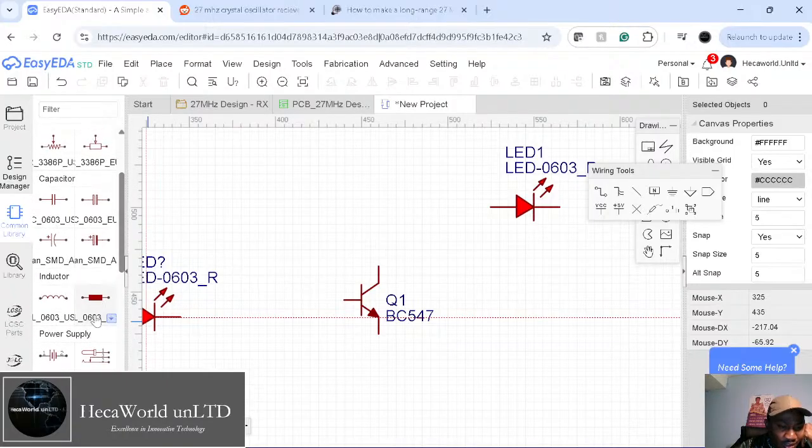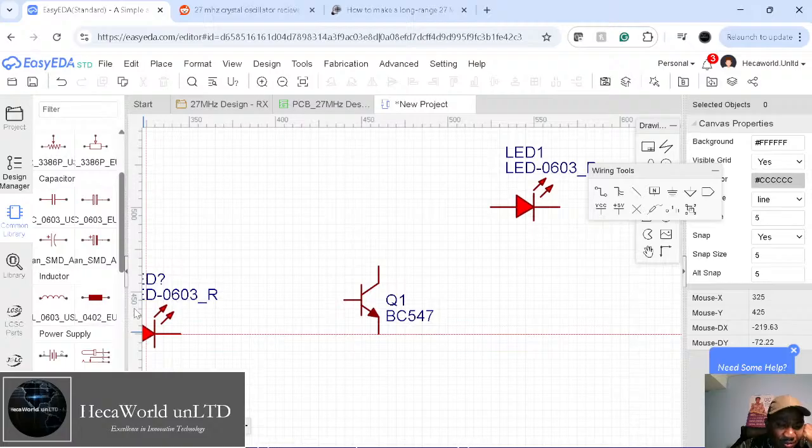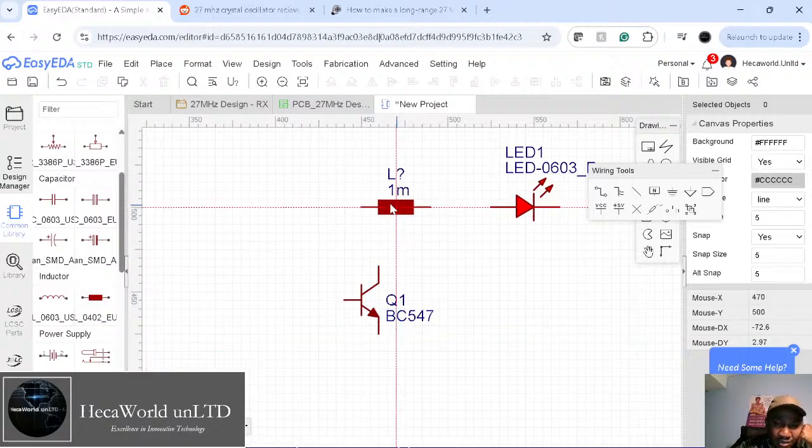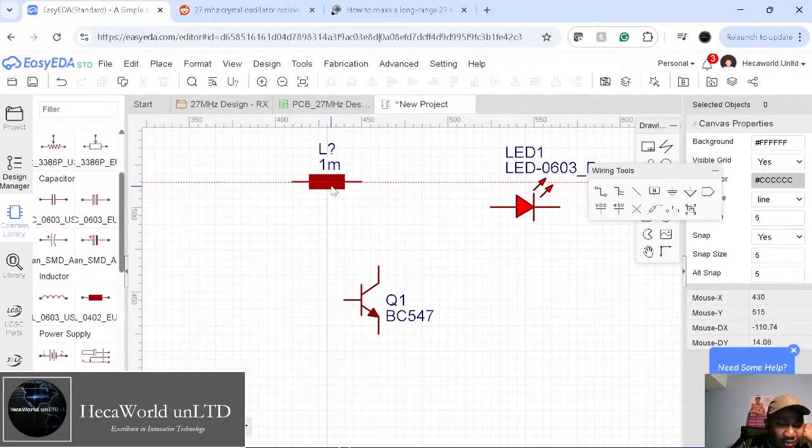Okay, resistors, we're going to make it surface mount. So let's do 0805. I think it's going to be a little bit big. Okay, let's do 0402. Sorry, 0402, and then we're going to pick that again. So place the resistors here.